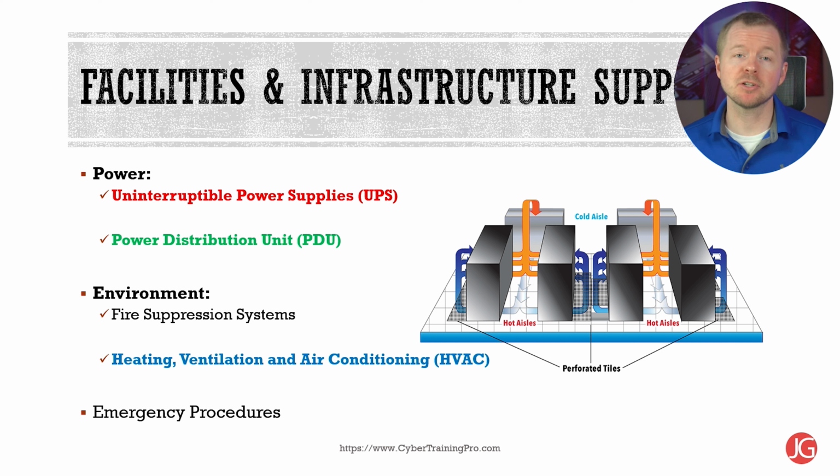Small racks might have a 20 amp dedicated circuit plugged directly into them, or in larger data centers, you'll see dedicated power transformers that the local power grid supplies. In addition to the standard power that your racks receive, you'll want an uninterruptible power supply, or a UPS, which is basically a battery backup solution. The UPS connects to a power distribution unit, or a PDU, which is a rack-mounted set of outlets for devices to use the UPS. Again, with large data centers, you'll most likely see power generators that run off petroleum or some other form of electricity in case that power goes down.